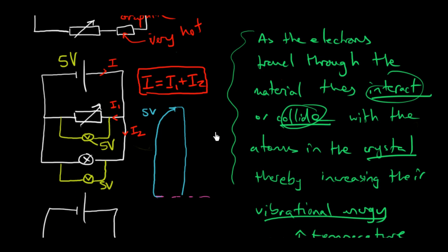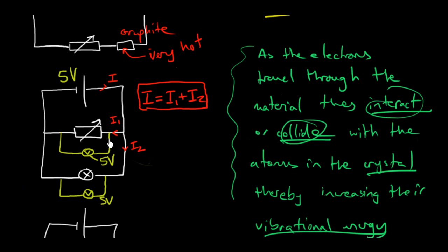In other words, the voltage is not shared in a parallel circuit. They both get exactly as much as is available, both branches, so it's not shared. Okay, if we do want to share voltage in a parallel circuit, you would have to connect something here in series with this, and now you have two things in series. Now the potential difference shares.